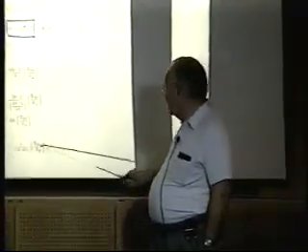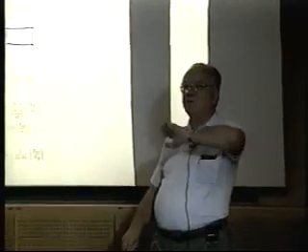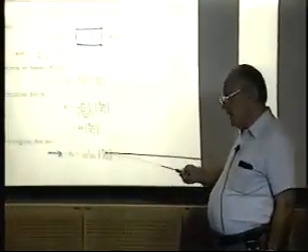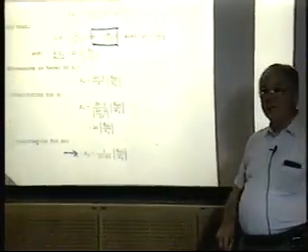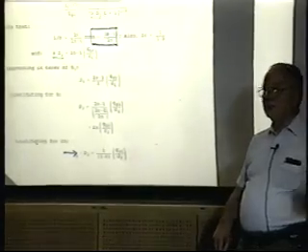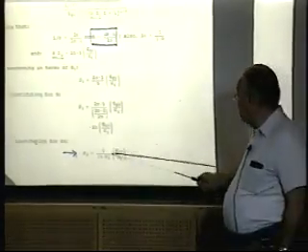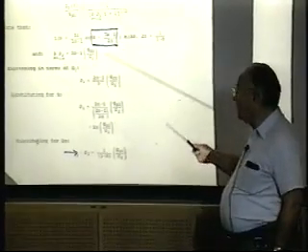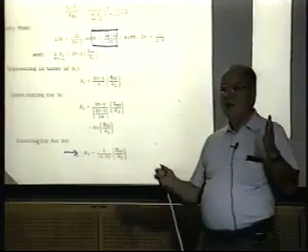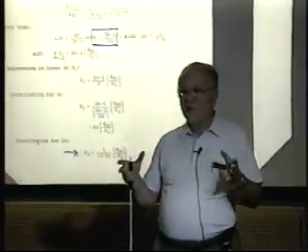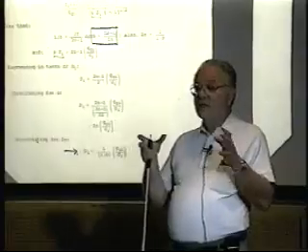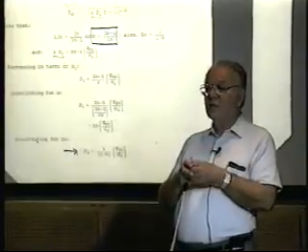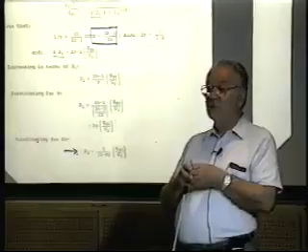Reservoir variables: at T equals 0 I have no performance data at all. There's my gas in place that I can get from geology. I can calculate a QGI from my KH and skin from a buildup. I can get the B value from the slope of the back pressure curve by including reservoir non-Darcy flow and the size of the tubing at the surface to get a wellhead deliverability curve, and that's the slope I would use.